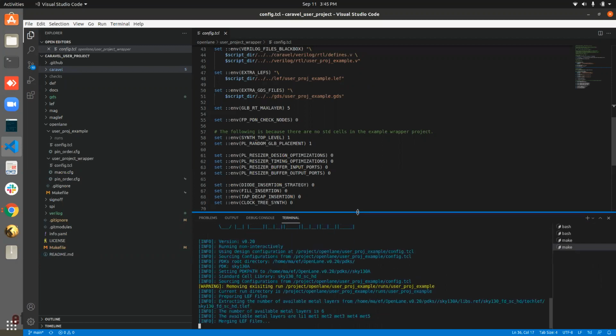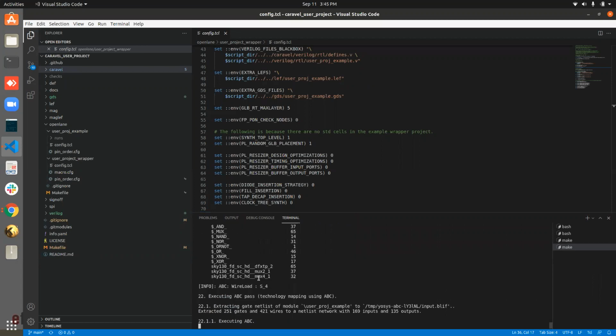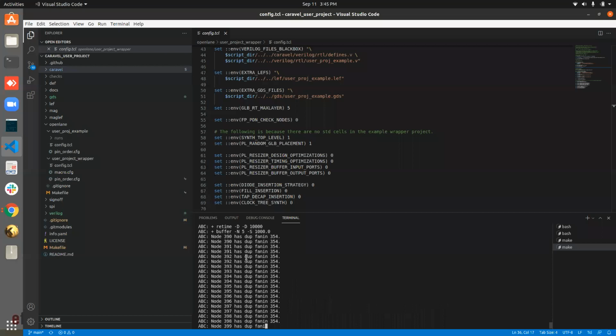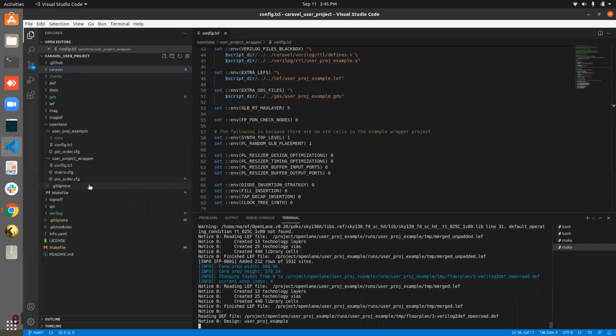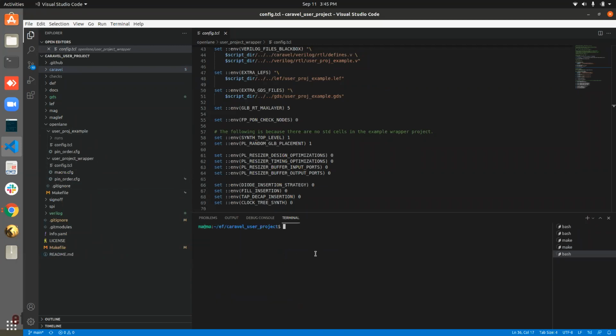So then it will start running OpenLane on the given macro name. Here it will also take a couple of minutes, so I will leave it running, and I will move on to installing and running the MPW pre-check.